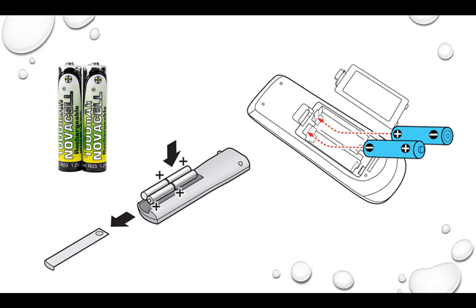These are examples of where batteries are in series, and I put this in here because when you look at them, they look like they're parallel because they're side by side like two parallel lines. But the fact of the matter is, if you look at the electrical connections in these, you'll see that it's negative hooked to positive because these are hooked together right here. So you've got this terminal that's positive, and current would flow this way and out the negative of that one.